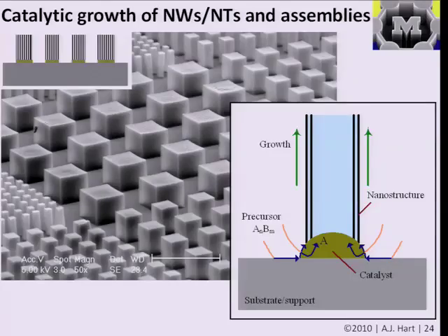And in some of these cases, we may, for example, start with particles on the surface, which can be formed by that initial film deposition process, and then introduce a precursor. For example, in the case of growing carbon nanotubes, this precursor could be, say, methane or acetylene or ethylene. And because of the way the precursor interacts with these catalyst particles, the atoms may attach, migrate, diffuse, and detach, and also flow away in a way that is favorable for interaction to grow this structure.